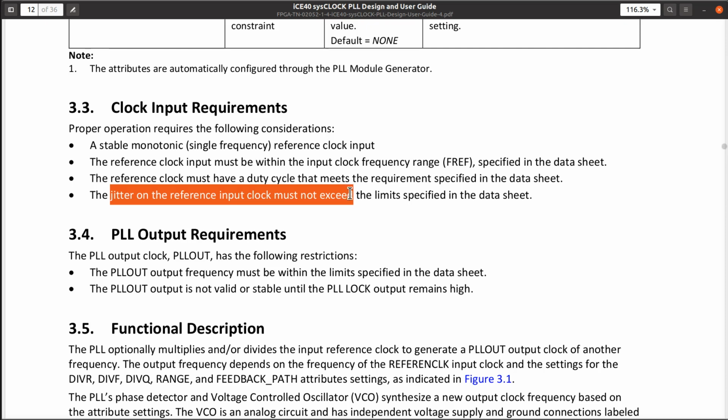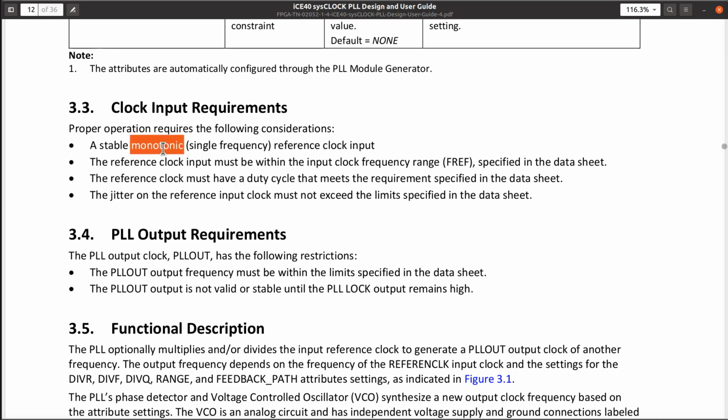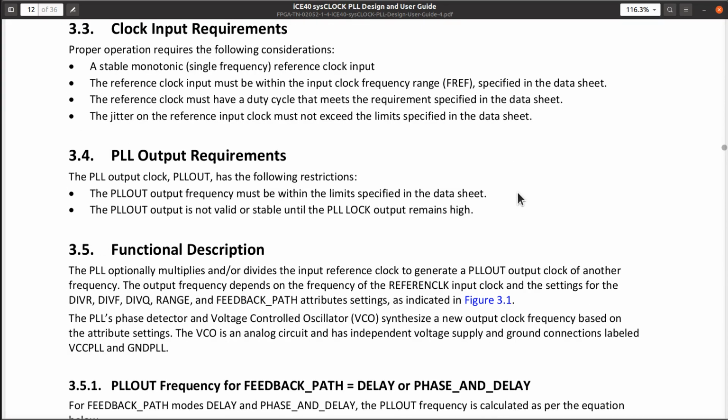Jitter. That's related to, does it run at a constant frequency? Are some pulses wider than the others, and so on? I mean, yes, they always will be. Nothing's perfect, and there are some specs on the data sheet. I'll leave that as a task to the viewer to look up all that fun stuff. A crystal can oscillator at 12 megahertz, 25 megahertz, 50 megahertz, even 100 megahertz should be perfectly fine for this, okay?